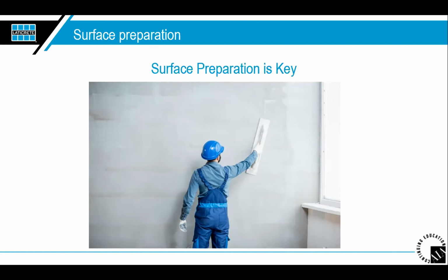I've even seen where they'll set tile outside during the installation process, and you see rain and dust because they're doing work outside, and you're seeing dirt being thrown up as well. Dirt can act as a bond breaker if they're not cleaning and sponging off those tiles before the installation. Water itself can act as a bond breaker.